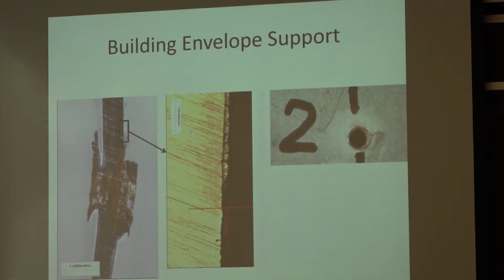What do I mean by that? On the screen here, I have a thin sheet of steel, and there was a self-drilling fastener thrown into it. I'll pass those around along with the cross-section. We're going to talk about that in surface modification. It has a drill bit on it, and it's galvanized. A very interesting component, because instead of having two processes, one where you drill the hole and a second where you come back and put a screw in it, it all happens at once.